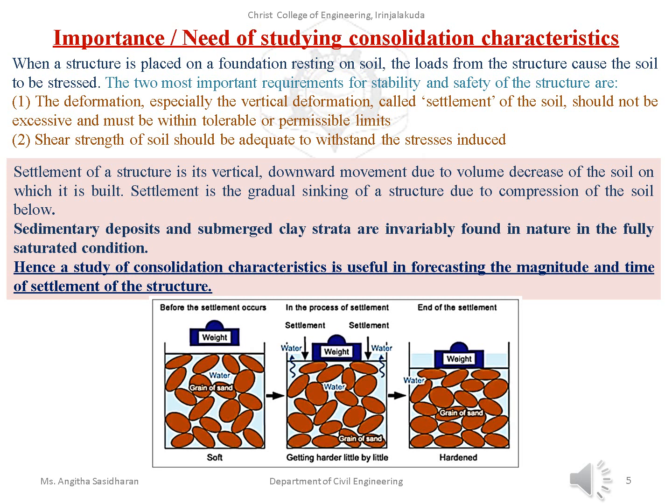Again, how is the study of consolidation related to this? Sedimentary deposits and submerged clay strata are invariably found in the fully saturated condition. So there is a chance for forceful expulsion of water from the soil mass, and there is a chance for consolidation.